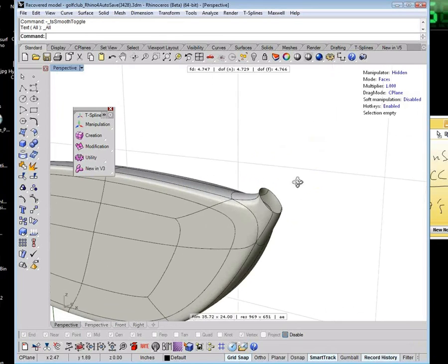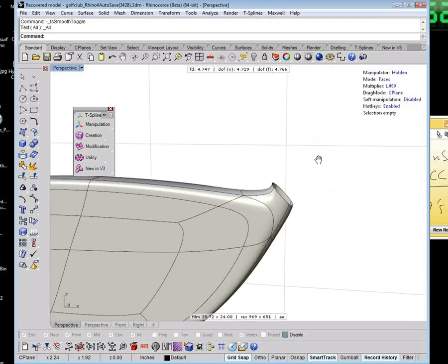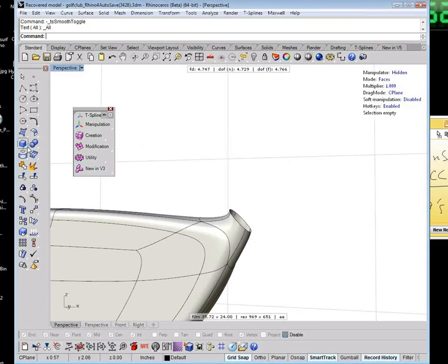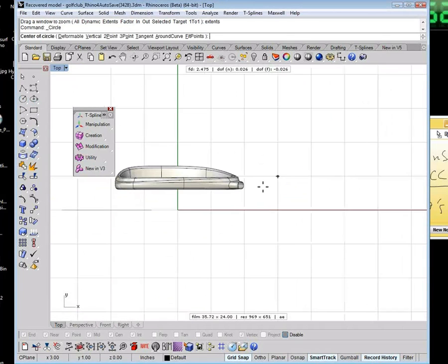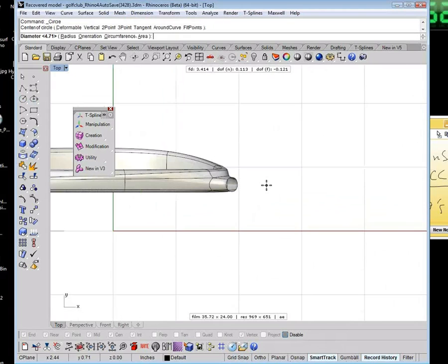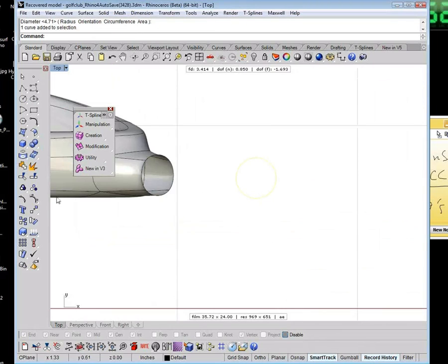So let's assume that I need to match this to a NURBS object. I can do a couple of things. I can take a curve, and let me just do this in NURBS real quick, just a standard Rhino curve. Just going to do this, and I'm going to check my edit points. I've got a whole bunch of edit points here. Actually, no, I'm sorry, those are control vertices. If I turn on the edit points, you'll notice I've got a lot of edit points in here.